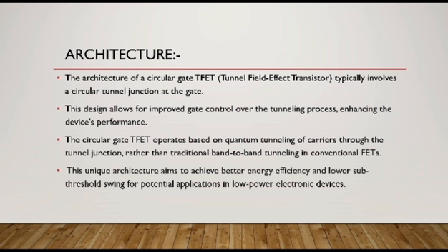The architecture of CG-TFET typically involves a circular tunnel junction at the gate. This CG-TFET design allows for improved gate control over the tunneling process, enhancing the performance of the device. The CG-TFET operates based on quantum tunneling. It carries current through the tunnel junction rather than traditional band-to-band tunneling in conventional TFETs. The unique architecture aims to achieve better energy efficiency and lower subthreshold swing for potential application in low power electronic devices.